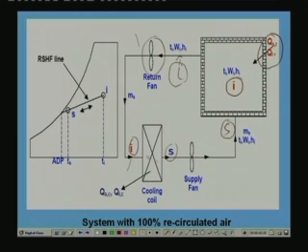So, in the cooling coil it undergoes cooling and dehumidification. So, at point S you have cold and dry air, okay, and the same cold and dry air goes to the building. So, we have a supply fan here. You may also have a return fan. Okay, return fan is an option, and as I said, all these lines are the ducts through which the air flows. Okay, and the same process is shown on a psychrometric chart here.